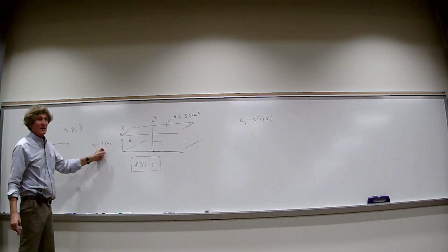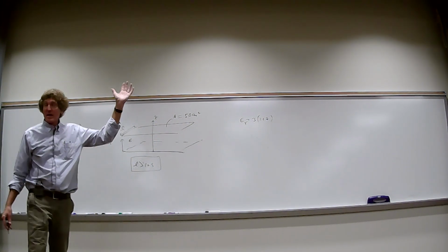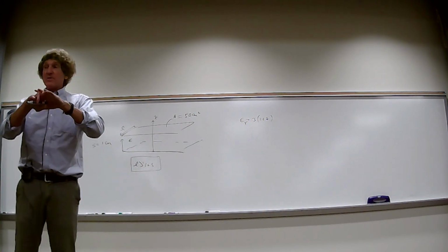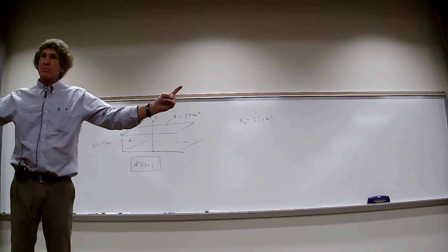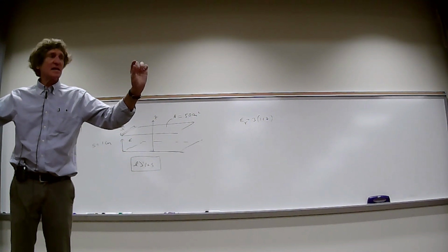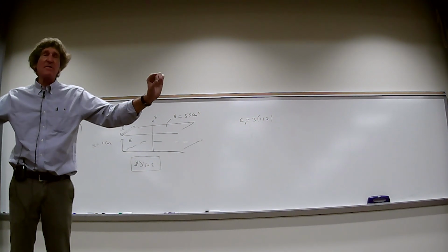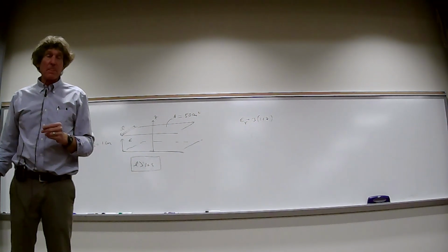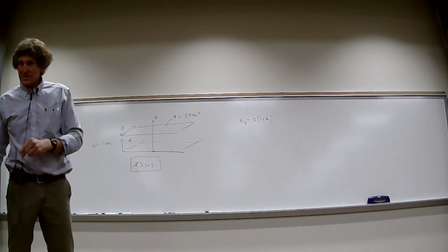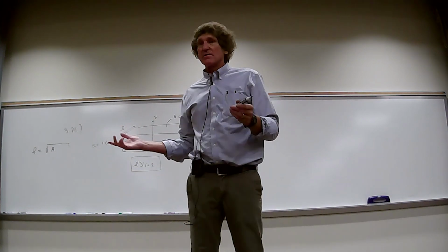So this problem, one thing I'm going to tell you is this problem would have fringing. I'm going to help you understand at least what I'm getting at here. Normally, when you say parallel plate, you want the plates, or any dimension of the plate, to be at least 10 times the separation distance between them, typically 50 to 100 times, for a parallel plate capacitor to work.